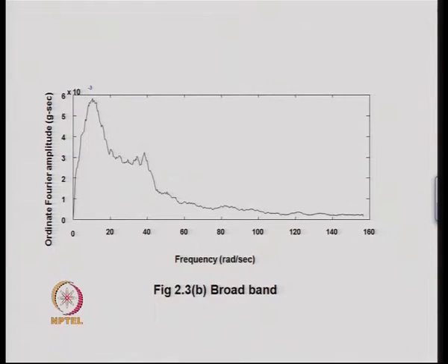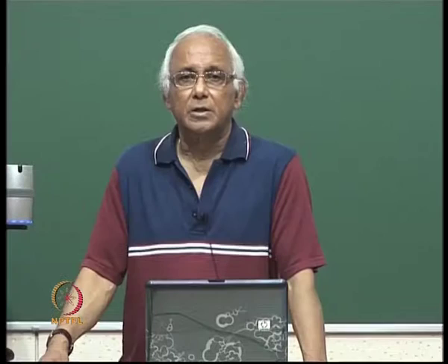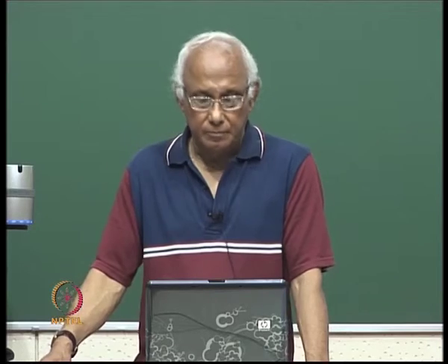Generally, broadband earthquakes are seen for hard bedrock or hard soil, whereas narrow band time histories of ground acceleration are observed for soft soil conditions.